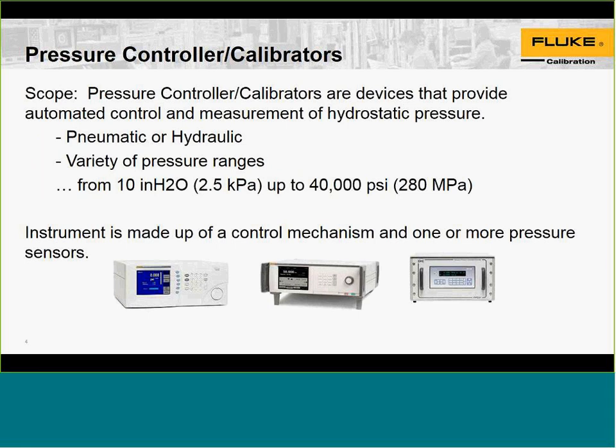Pressure controller calibrator. A pressure controller is an instrument that provides automated pressure control and measurement of hydrostatic pressure. They perform two functions: they control pressure and they measure pressure. And the fluid is in a stable condition, as I mentioned, hydrostatic. Even though the pressure controller sometimes pulses pressure or uses temperature to control pressure, it is essentially a static situation to the best of its ability.